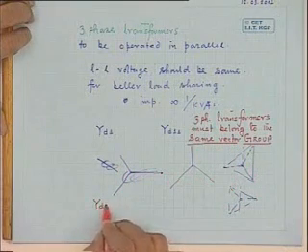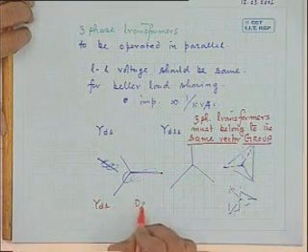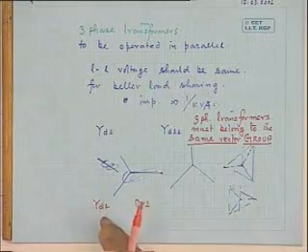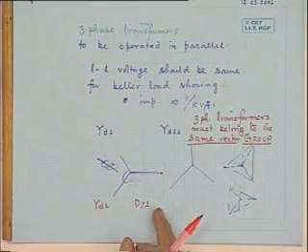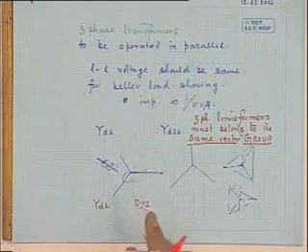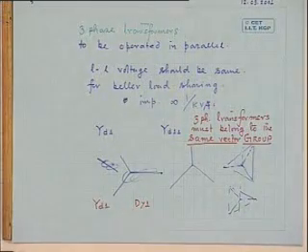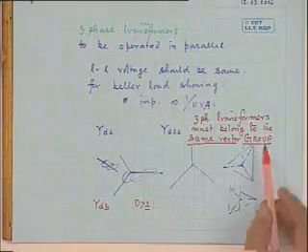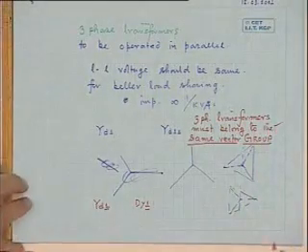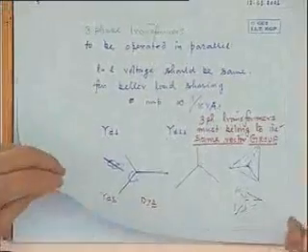Of course, this means that you can connect YD1 in parallel with DY1. That will do. Let this be star, this be delta, primary be delta, this be star. You will first see whether line voltages are the same, not phase voltages, line voltages are the same. That you will ensure and see that the shifting of the voltages is by the same amount so that you can successfully parallel them. So this must be understood very clearly. I will give you some problems on parallel transformers later.